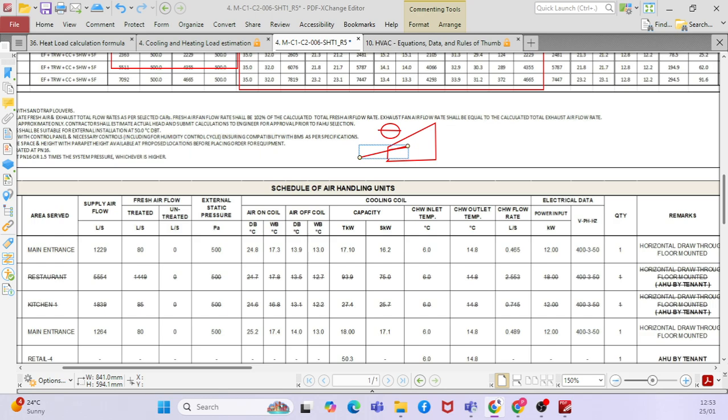That is what relative humidity means. When you say 100% moisture, the air is full of moisture. So what will happen? That moisture will become water, and that water is the condensate drain. Remember, when you see the FCU, you have a condensate drain. When the air passes through the coil, it tries to reduce the temperature in such a way that there is no dry air. That means the dry bulb temperature and wet bulb temperature will be the same. That is called saturated, basically.